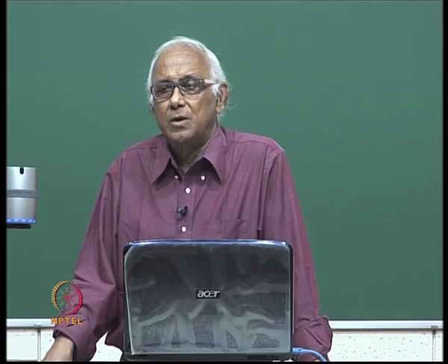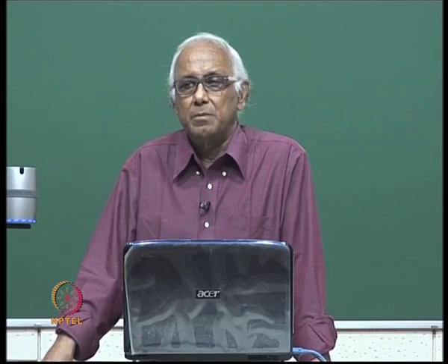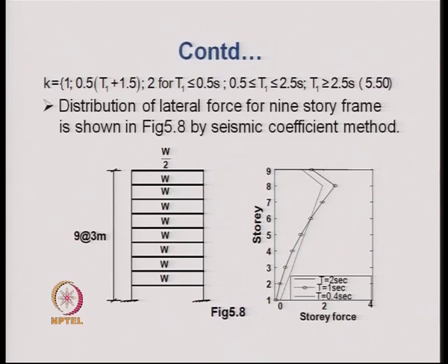Mind you that the base shear that was calculated was obtained by multiplying the total weight of the structure by the seismic coefficient Ch obtained for the structure's period calculated by Rayleigh's approximate method.